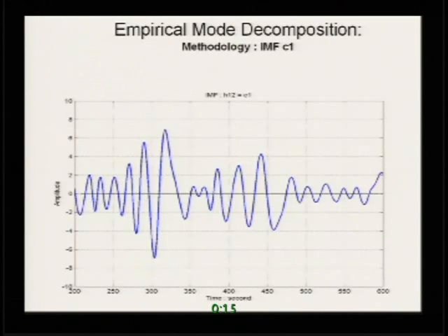So in his study, what he finds is that if the noise is Gaussian, and if the extrema number equals the zero crossing number, then this has to be narrow band. That means the frequency has to be very, very concentrated in just one single frequency. But when we look at this signal, we find this signal is not narrow band at all.